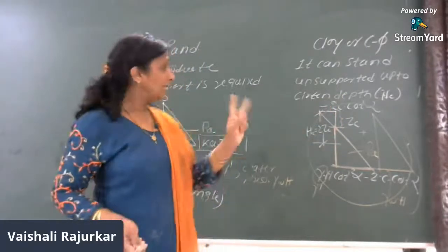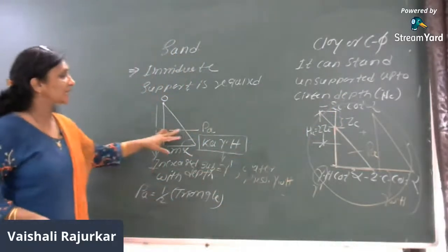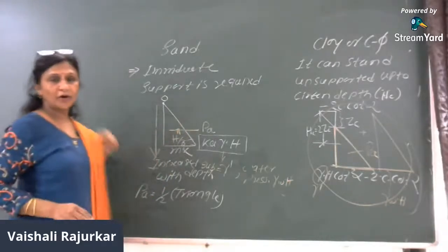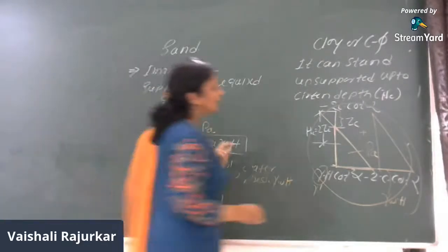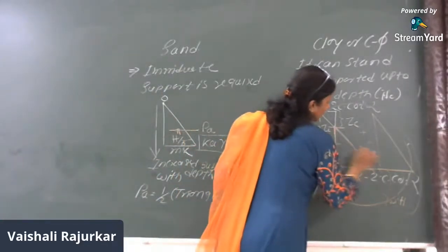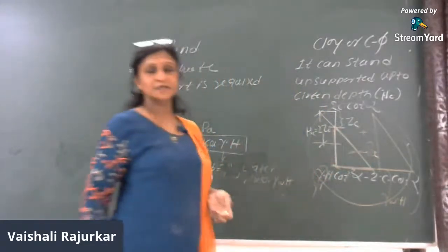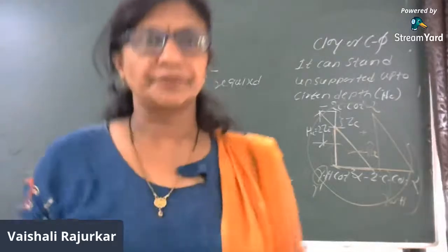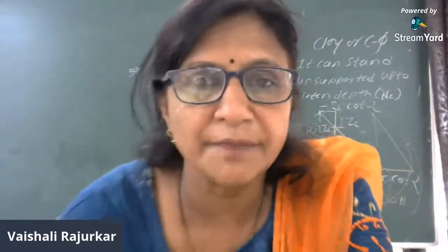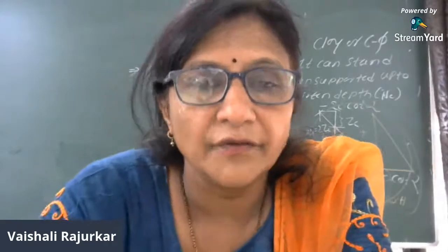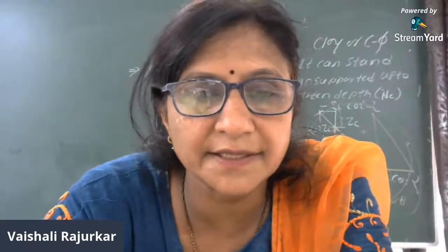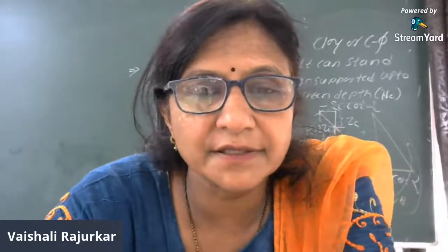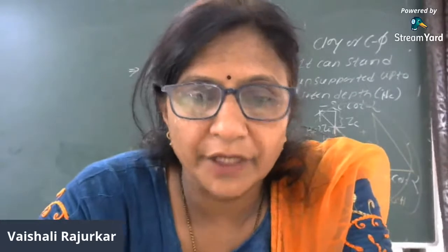When you calculate the total distribution, you have to combine these two diagrams and then calculate the earth pressure. Then whatever area you are taking into consideration, the CG of the triangle will be at h by 3 distance from the base of the area which we are taking into consideration for the diagram. I think there will not be any doubt in this. So with this, our second unit, that is the earth pressure, is over. In the next class, we will discuss the pile foundation, right?